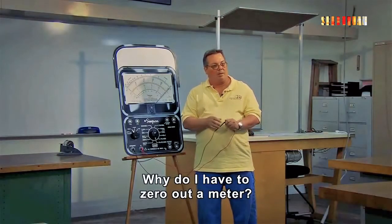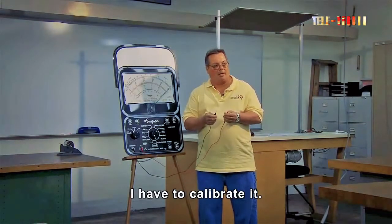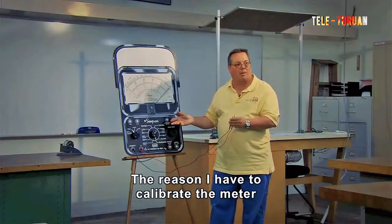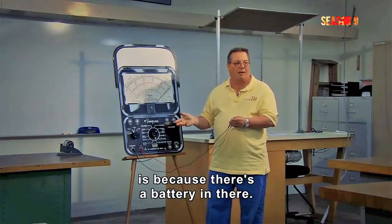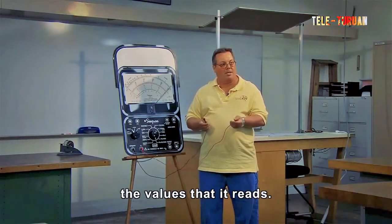Why do I have to zero out a meter? Well, if I want to get an accurate resistance reading, I have to calibrate it. The reason I have to calibrate the meter is because there's a battery in there. And as the battery weakens, it's going to change the values that it reads.